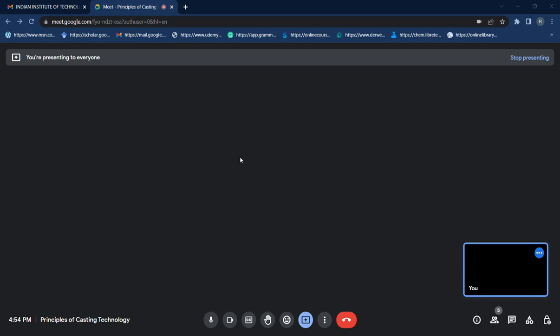So for the feeding distance in steel plates, you can see here, this is your riser part. The plate has a thickness of T. Then the riser can feed at a maximum distance of 4.5 T to the left and 4.5 T to the right part. It is assumed that your edge is here. So the riser generally contributes 2 T only, and 2.5 T is contributed from your edge contribution, because from the edge also solidification will come.